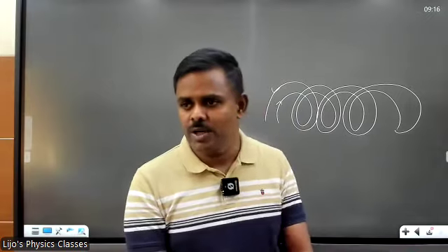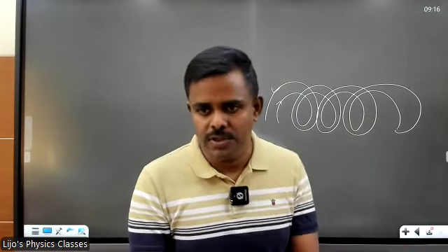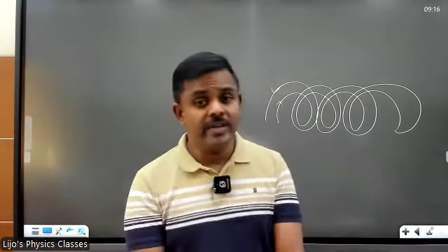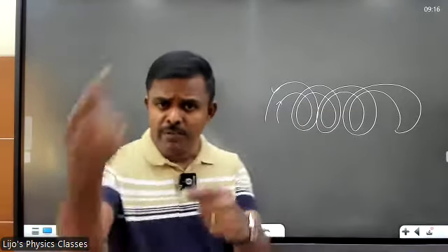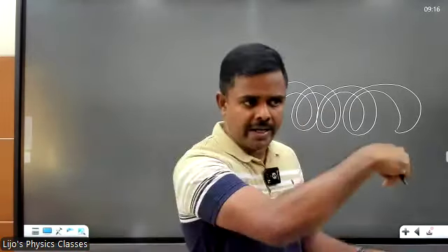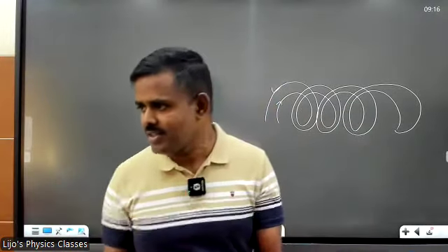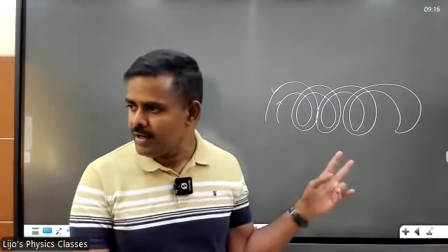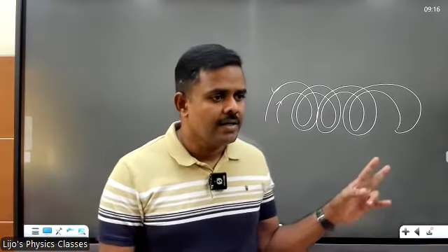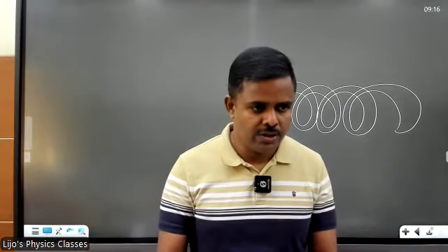What we need is pure resistance for the coil. Got it? So how can we achieve this? Just by winding one coil. When you're done winding, stop there and wind it in the reverse direction. Got it? So that induction due to one coil will be nullified by the other coil. This is called non-inductive winding.